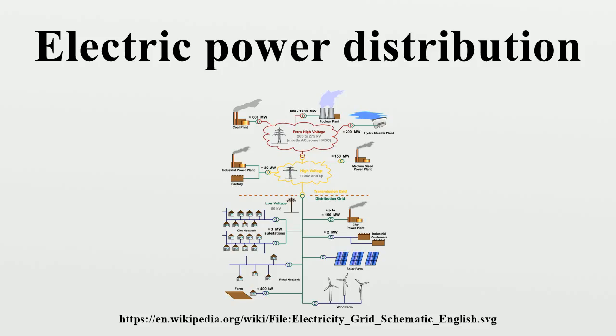History. First commercial distribution of electric power: in the very early days of electricity distribution, direct current generators were connected to loads at the same voltage. The generation, transmission and loads had to be of the same voltage because there was no way of changing DC voltage levels other than inefficient motor generator sets. Low DC voltages were used since that was a practical voltage for incandescent lamps, which were the primary electrical load. Low voltage also required less insulation for safe distribution within buildings.